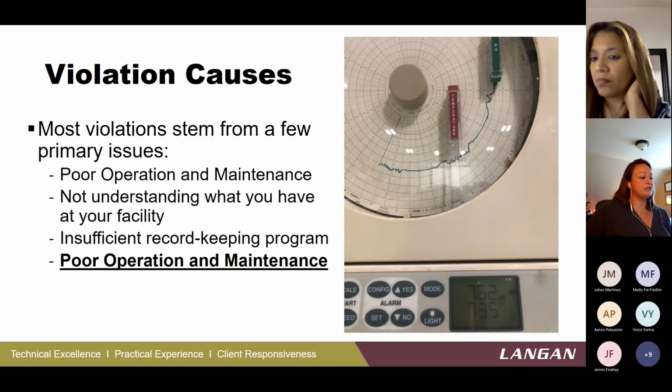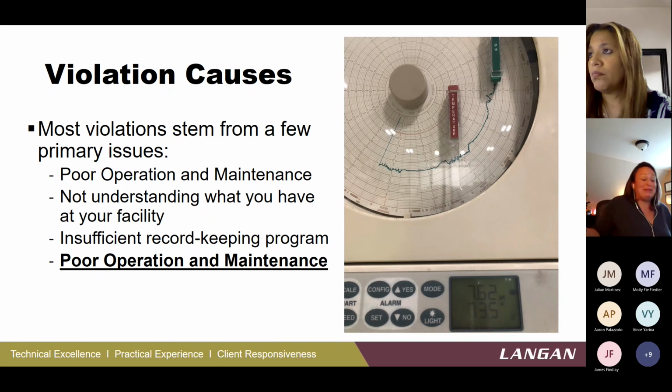Maybe your infrastructure or your treatment system is just aging. Maybe probes are acting up. pH probes are frustrating little devices. Sometimes they get very picky. They don't want to do what they need to do. So for operation, you need to be doing regular checks, regular calibration, regular cleaning. A lot of times when violations happen, particularly in terms of pH, the first thing we ask is: was the violation real? Did it really happen? Or was it just a probe drifting and getting wonky because it hadn't been cleaned or calibrated in a while?